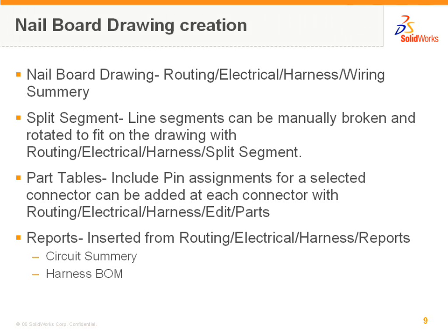And finally, we can drop in some reports into this drawing, a circuit summary and a harness bill of material. In order to drop in the reports, it's from the pull down routing, electrical, harness, and reports. With that, we'll go into SOLIDWORKS and I'll show some of this.